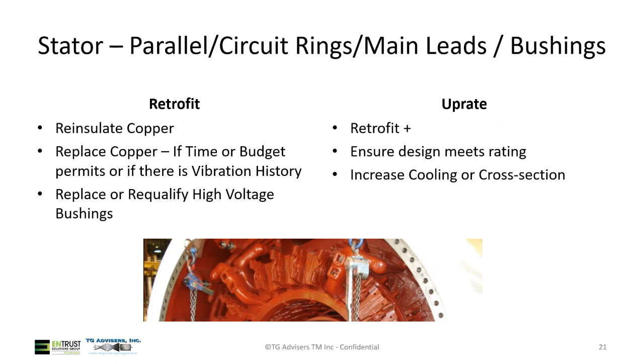So for bushings, in all cases, you'll want to replace or requalify your high voltage bushings at this time. They typically get forgotten about just because they just work. So in a lot of cases, it's just a forgotten component. But this is a really good time to go ahead and replace those with the overall scope. That's mostly because it takes a little bit of time to do, and it can be done in parallel with the other work, so you don't have to take another longer than expected outage later on.